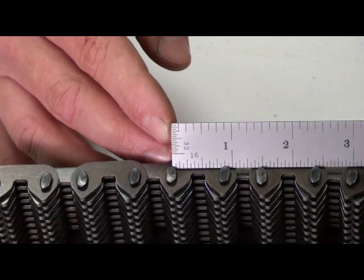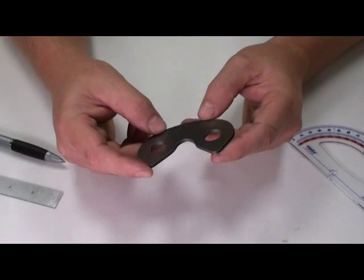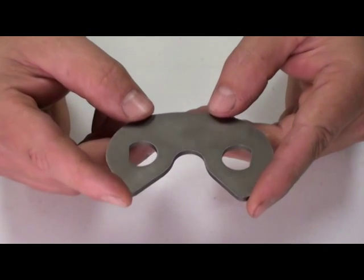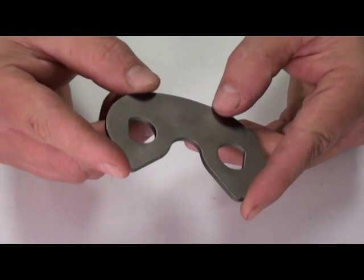Pitch is most commonly expressed in inches, even when other dimensions are given in metric units. In order to accurately measure link flank angle, it is necessary to remove a single driving link from the chain. Here is a sample driving link that we removed.